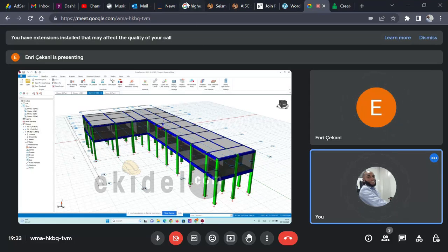Okay, then we now go to what they call sliding shear. When it comes to sliding shear, I think EuroCode was the first to introduce what they call bi-diagonal reinforcement. Over the years, most of the buildings, even if they were able to withstand the effect of the earthquake, you will see that most of the members would fail in shear. So when this code came into existence, EuroCode, they introduced bi-diagonal reinforcement for ductility class high.